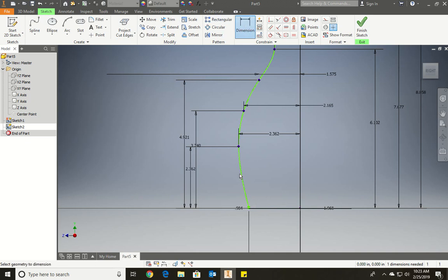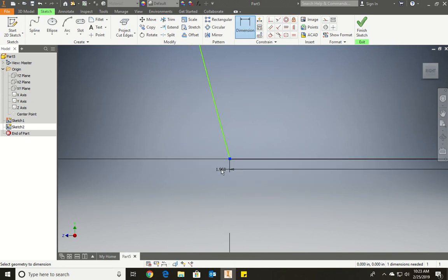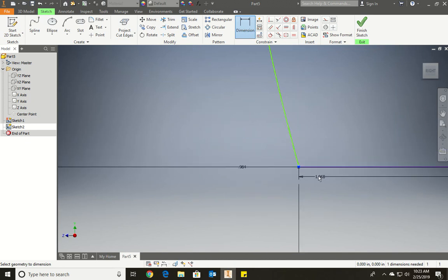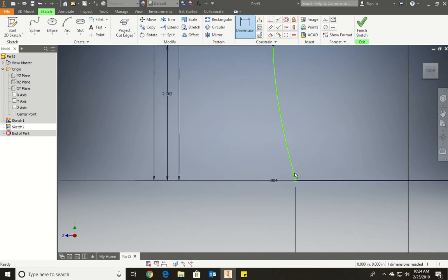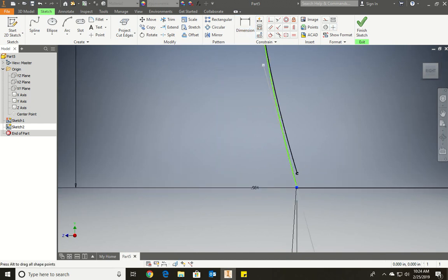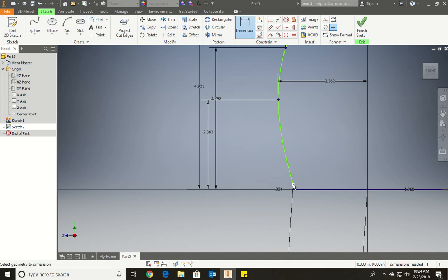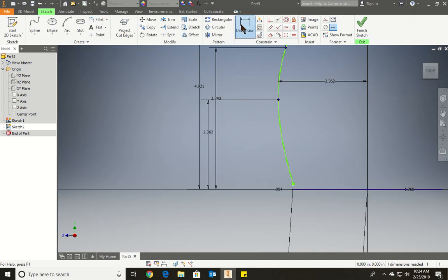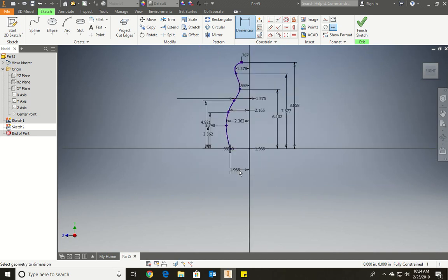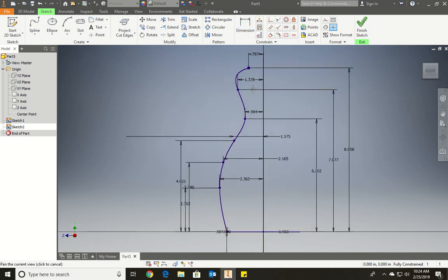And we should do what? So how will we do the 0? We click on the point. We click on this. Zoom in a bit. It doesn't let me do 0. Why? If it doesn't let you do 0, what's another way of making it? There we go. I lost the button. Dimension from here to here, 0. Okay? And as you can see, it's fully defined.